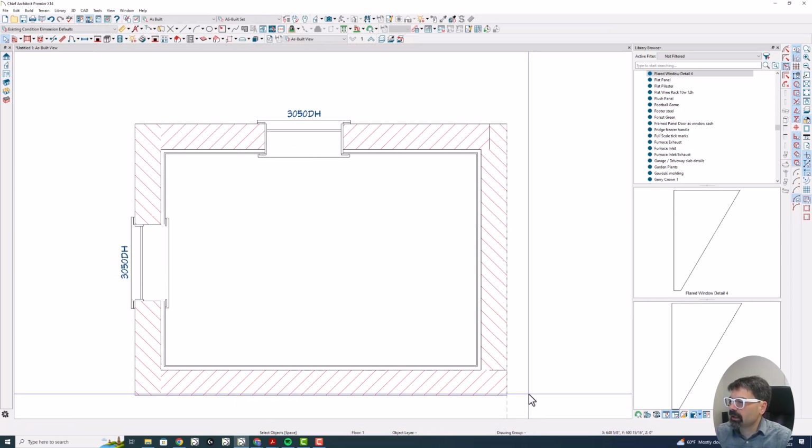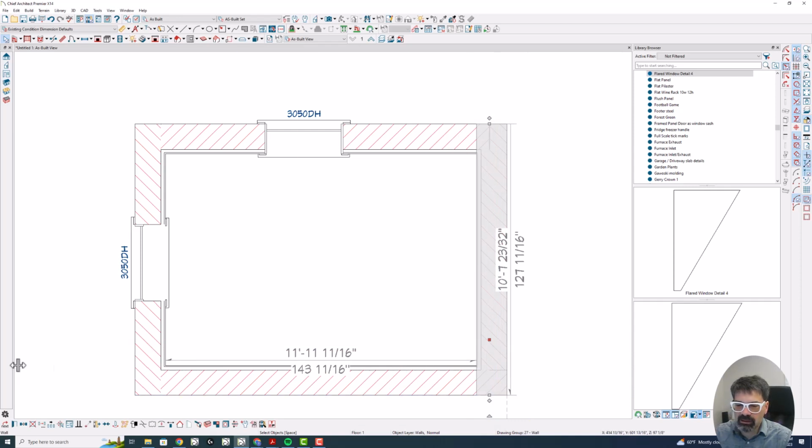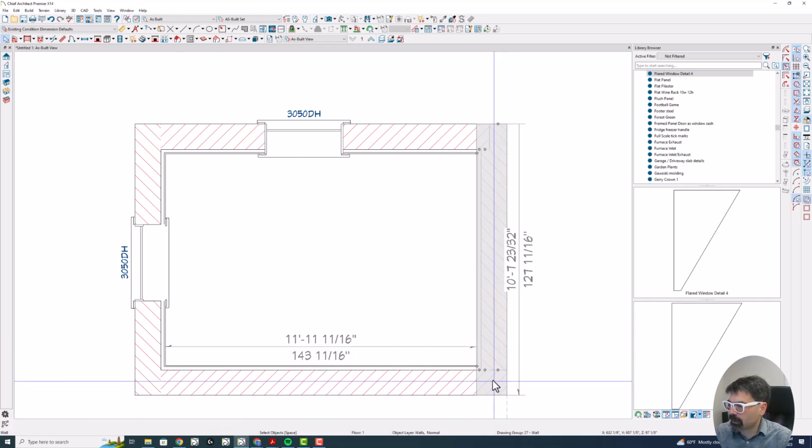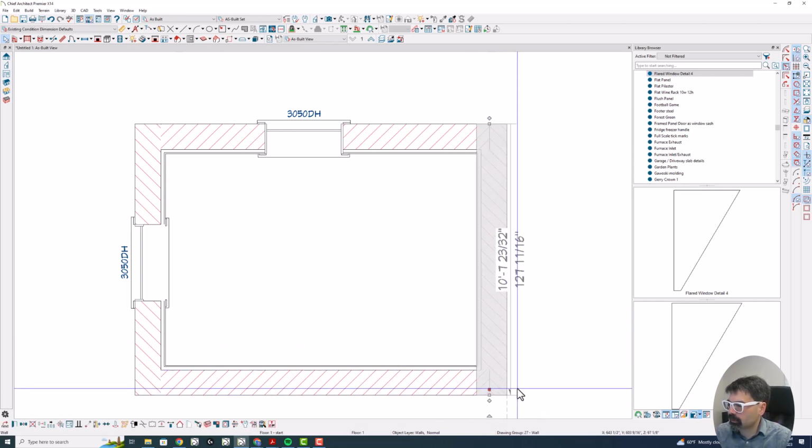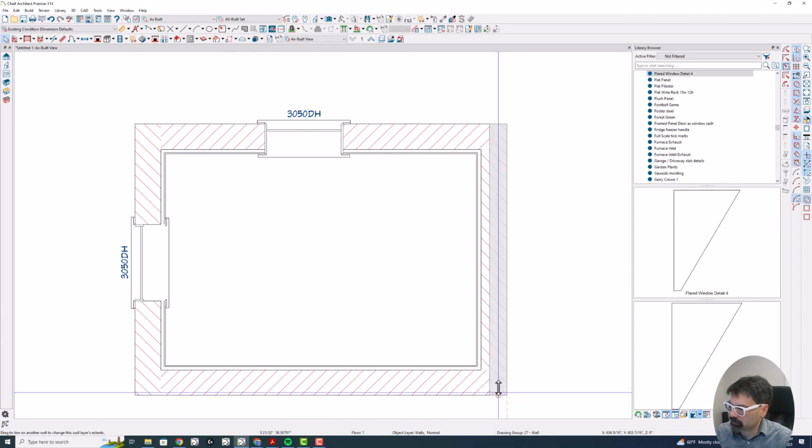Now, because I have this wall type that has one layer across here, meeting at a corner to this wall type that has 2 layers across here, that's where this line comes in and this line comes in. This line would be here, but I adjusted some of the end like that. So I can adjust the intersecting points, wall intersections.